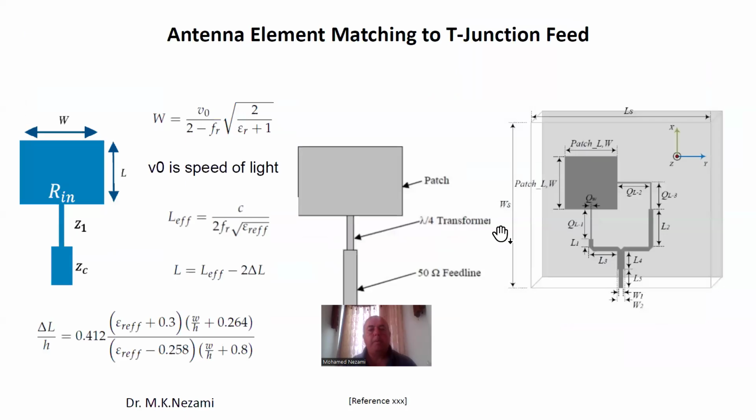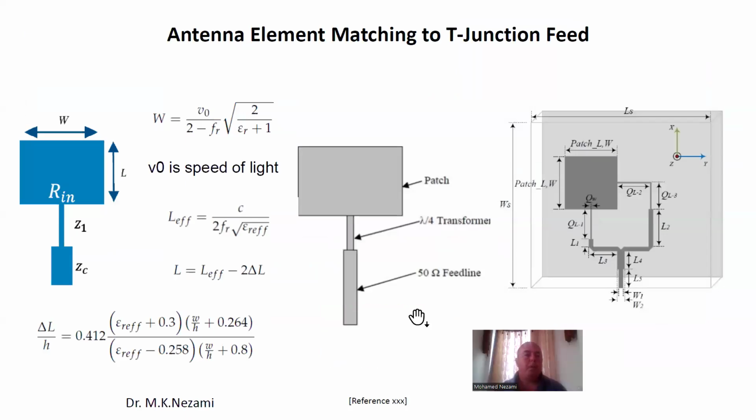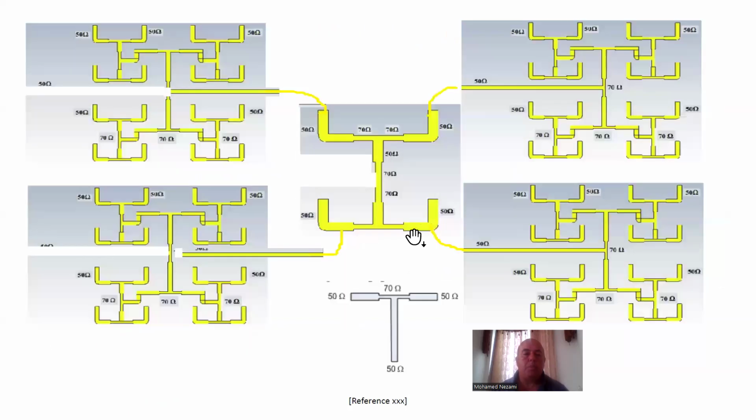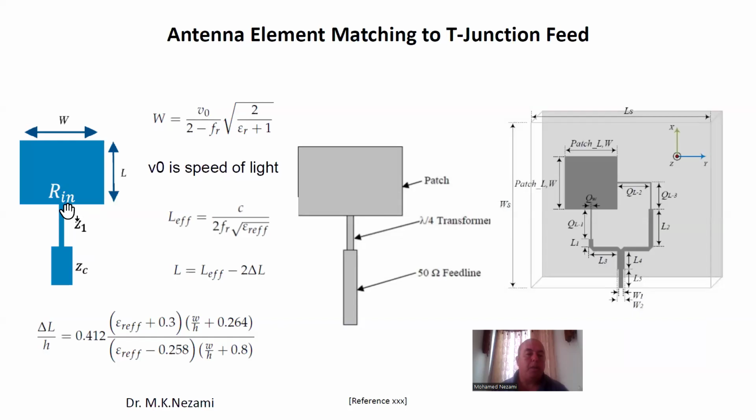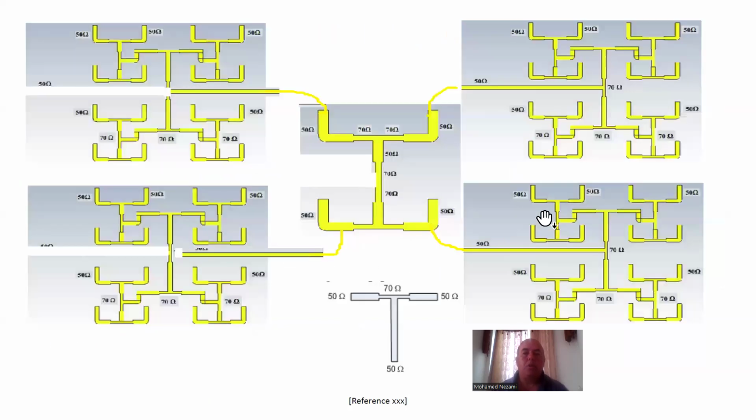So, okay. Now, of course, the antenna itself, now there are two ways to approach the antenna. I'm not trying to be an antenna designer over here, but if you're dealing with the patch usually the dimensions of the width and height and the input impedance is well established. So these are the equations, depending on your resonance frequency, where you want the patch to resonate at. The reason I want to deal with this is because this plays out the input impedance of the antenna itself, the element itself, can reduce the complexity of the array, of the feed, the antenna, the passive feed network.